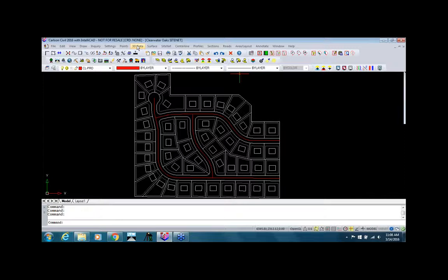changes now to the right of Points. I've got 3D Data, Surface, essentially a duplicate of what's in Survey, but with some additional tools. SiteNet is specific to Carlson Civil for producing design and material quantities. Centerline is essentially a duplicate of what we get in Survey, so there is some overlap. Profiles, a much more robust menu than Survey does have profiles. It's located under the Surface menu in Survey. Sections is exclusive to Carlson Civil, as is the Roads menu. Area, Layout and Annotate are basically duplicates of what you get in Carlson Survey.